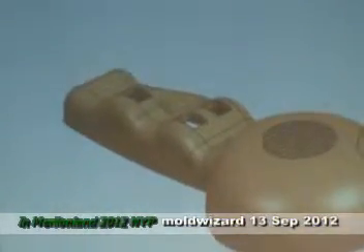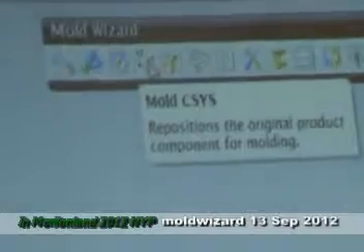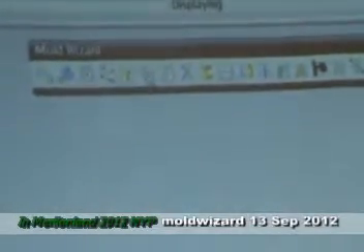So we have used the first button, the second button. Fifth, now we need to go to define a block. The Define Block button is the button for putting in the block. Most of the time I don't change it because I can change this kind of size at any time. Anytime. So I just click OK. This is the workpiece. If the block is big enough to cover up the product, that should be okay for the cutting process.